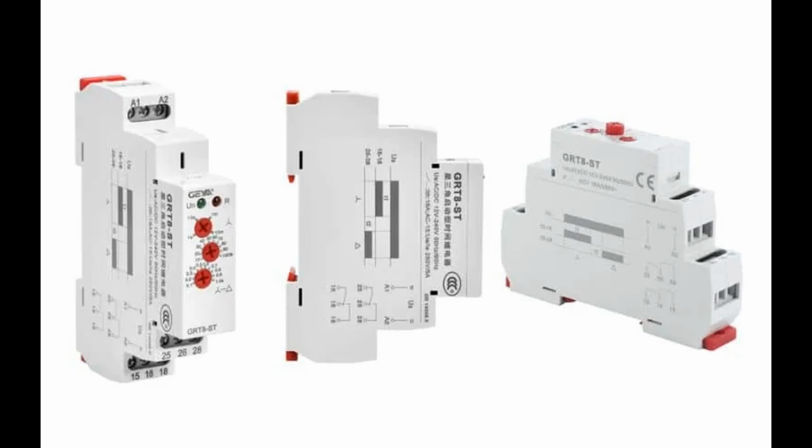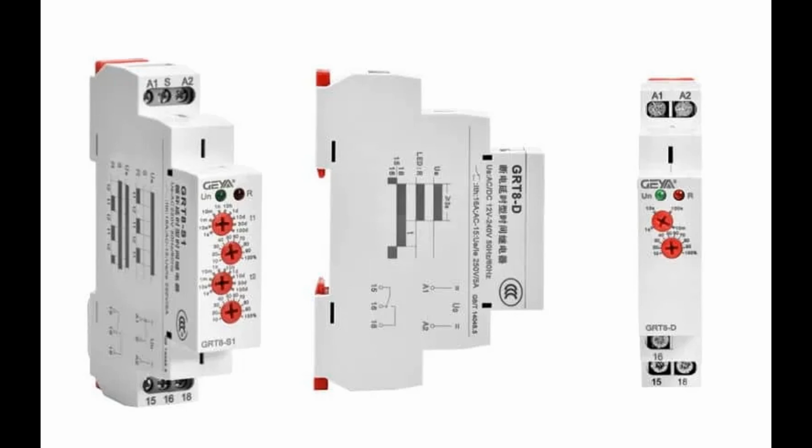Derating considerations. In certain operating conditions, such as high temperatures or altitude, the voltage and current carrying capabilities of the relay may need to be derated to ensure reliable operation. It's important to consult the relay's datasheet or manufacturer's guidelines for any derating factors that may apply in specific environmental or operating conditions. By carefully considering the voltage and current ratings of time delay relays and ensuring they align with the requirements of the application, you can ensure safe, reliable, and efficient operation of the electrical system.